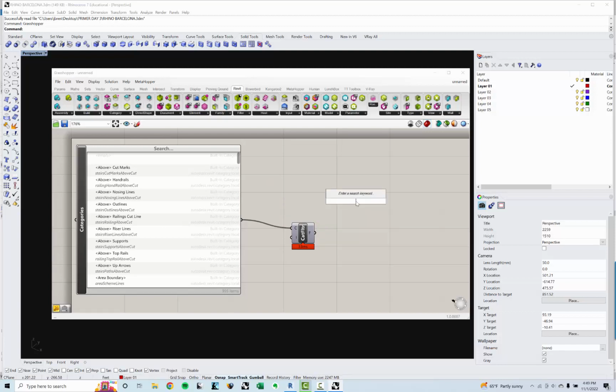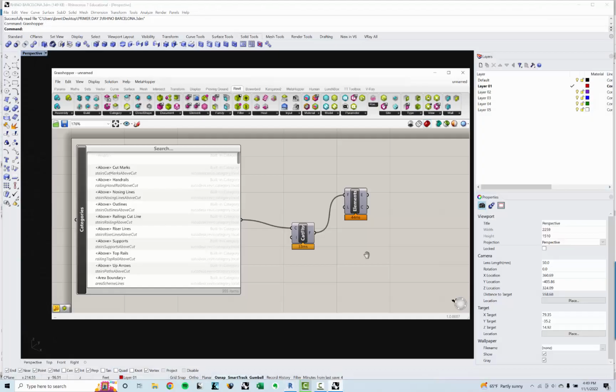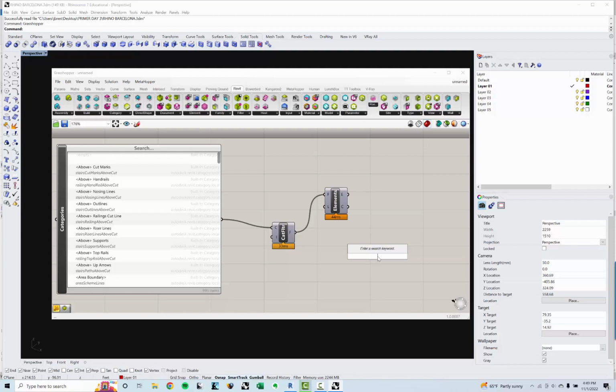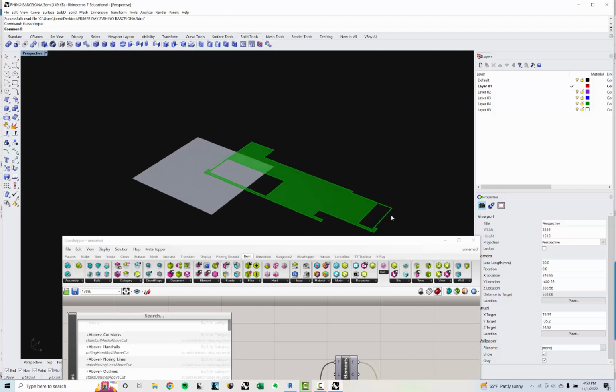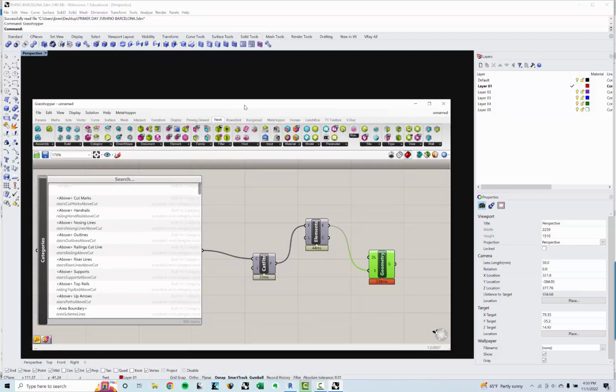The next thing I'm going to do is go to query elements, and I'm going to run the filter into here. So if I do a panel on this, you can see that it's giving me the generic floor that's in there. I only have one floor in there. And I should see it, right? I'm not going to see it because Rhino.Inside requires you to have a geometry visualization thing in here. So the last component I need to put on here is element geometry. If I click here and go to that, it's going to think for a second and show me the floor. So it's not in Rhino yet, because as you know, the way that Grasshopper works is it visualizes it and the geometry is not quite there yet.